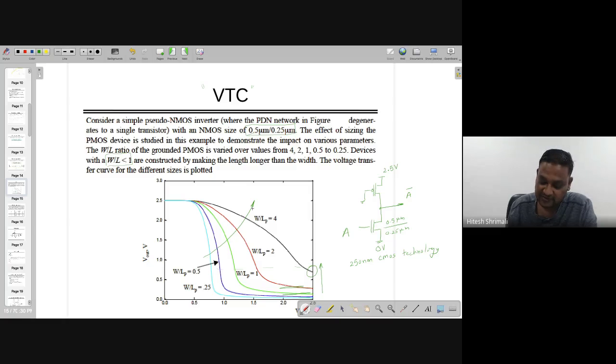And when you are doing this, you have a better characteristic, and similarly you can design it for a given VT, given VM, and for given noise margin high and noise margin low. All these things can be done, or you can design it for the given VOH, VOL, and other things, right? So this is not so difficult in that case.